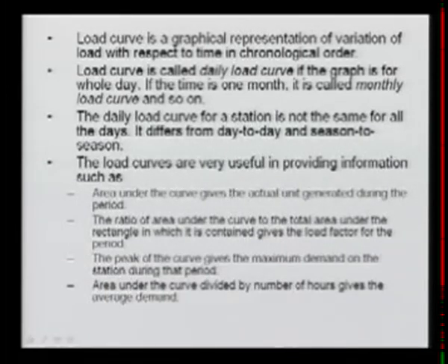The daily load curve for a station is not the same for all days. It differs from day to day and season to season. So for analysis purposes, we normally go for the various seasons like summer, winter or monsoon, and based on that we analyze. Load curves are very useful in providing information such as: the area under the load curve gives the actual units generated during that period.